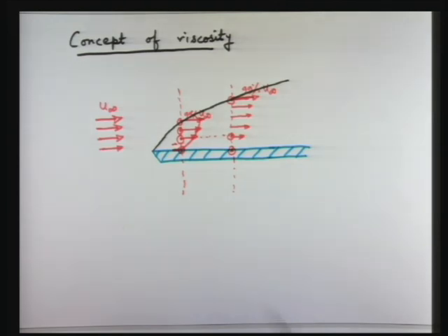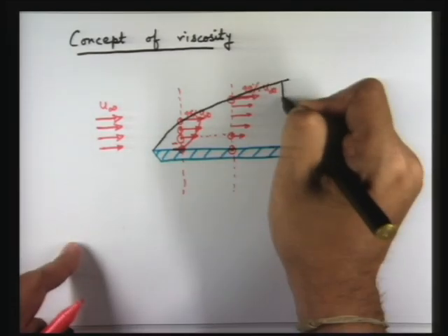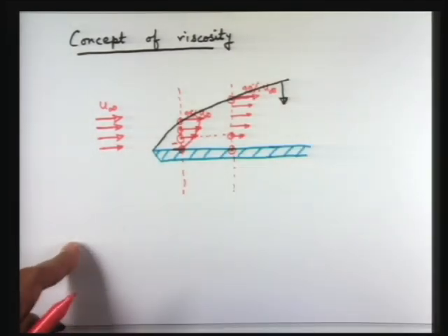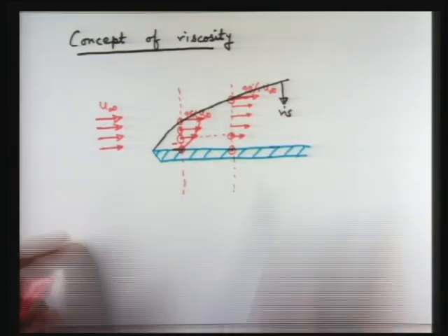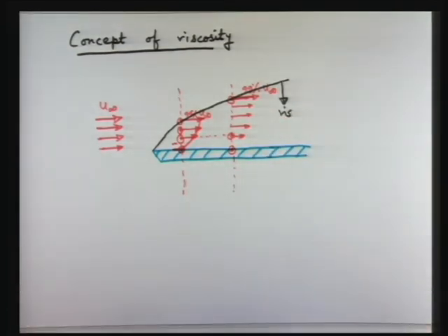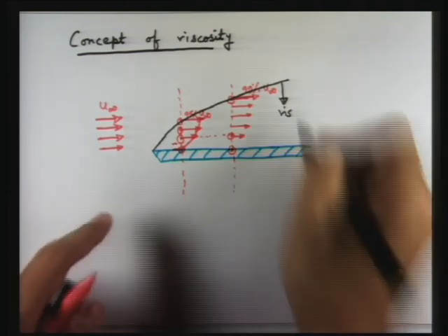So this is an imaginary line, this black line. It does not exist in the fluid. This black line is an imaginary line and it demarcates the flow region into two parts. The lower region is where viscous effects are important. Remember that the fluid has viscosity everywhere. It is just where viscous effects are important and where viscous effects are not important.